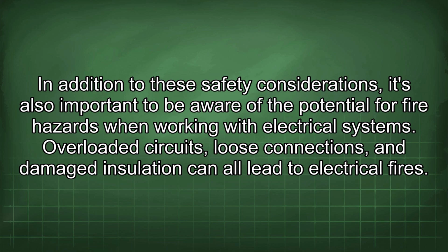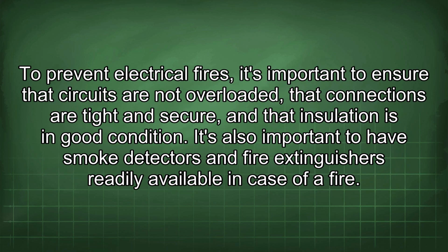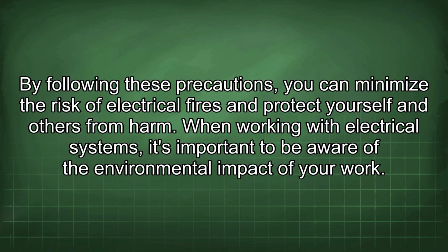In addition to these safety considerations, it's also important to be aware of the potential for fire hazards when working with electrical systems. Overloaded circuits, loose connections, and damaged insulation can all lead to electrical fires. To prevent electrical fires, it's important to ensure that circuits are not overloaded, that connections are tight and secure, and that insulation is in good condition. It's also important to have smoke detectors and fire extinguishers readily available in case of a fire. By following these precautions, you can minimize the risk of electrical fires and protect yourself and others from harm.